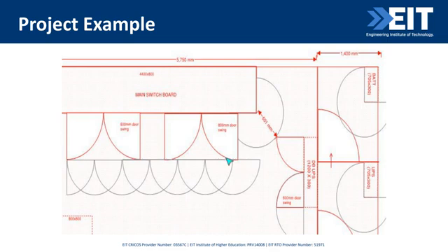Here's another example. This one's showing that we're calculating the clearances in front of these doors from other switchboards. So it's making sure that we've got that 600 mil clearance when all the doors of that switchboard are in the open position.